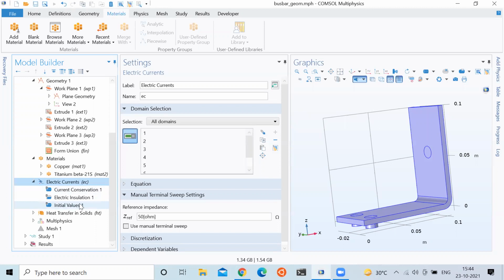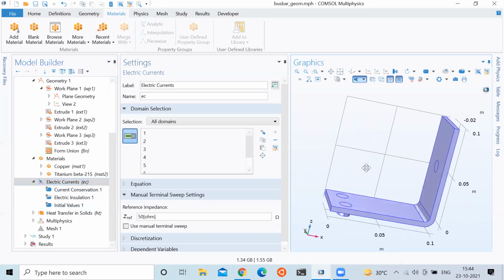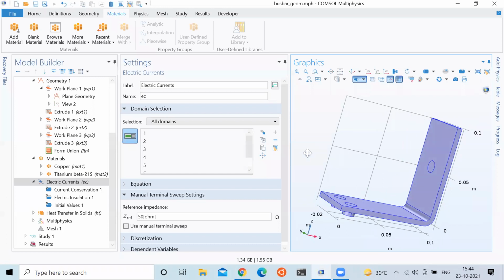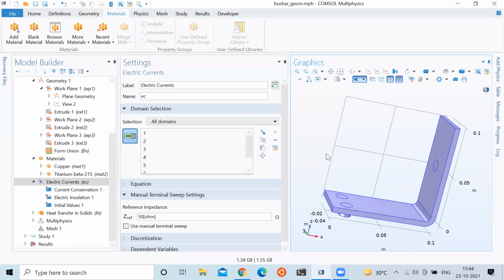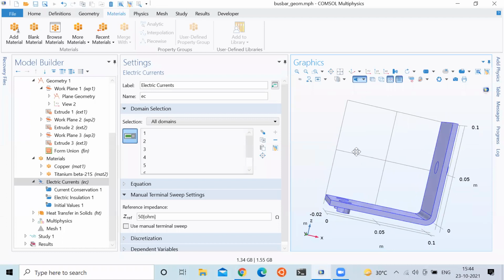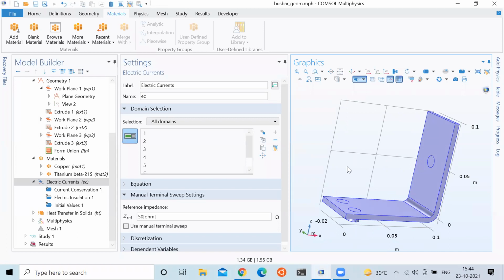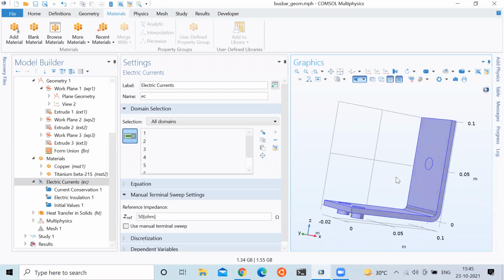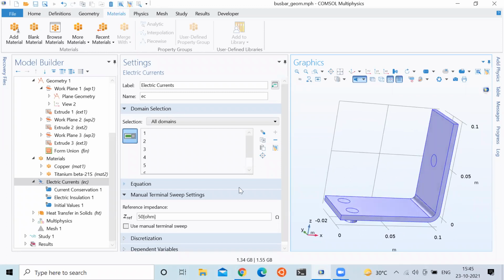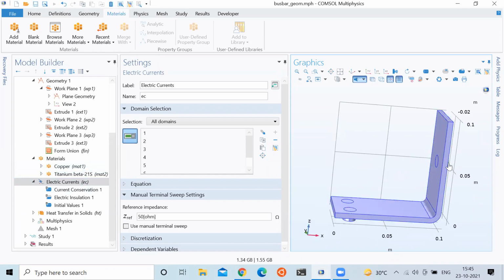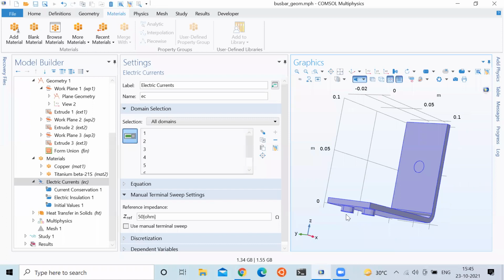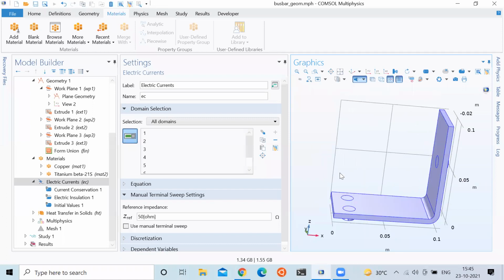boundaries and constraints. Okay. So now in this bus bar, we have to generate an electric current. Can anyone tell, to generate an electric current in this bus bar, what do we need? How can I generate electric current? I don't have any wires. Voltage at some of the bolts and a low voltage at the other bolt. Yeah, exactly. So we will specify a potential difference. At this bolt, I'm going to specify a higher potential, and at this, I'm going to ground. So this potential will be 0.